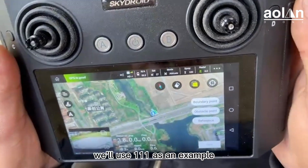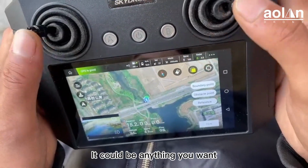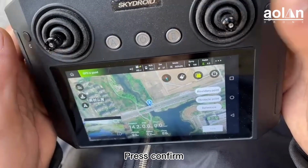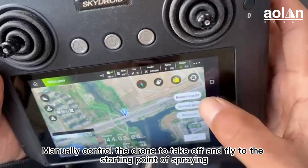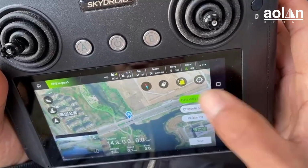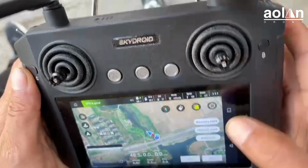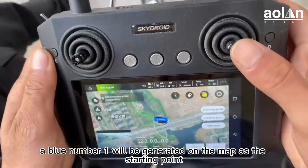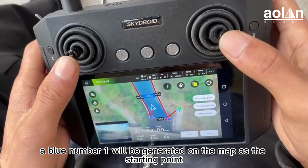In the video, we'll use 111 as an example. It could be anything you want. Press Confirm. Manually control the drone to take off and fly to the starting point of spraying. After hovering the drone, click Add Boundary Point. At this time, a blue number 1 will be generated on the map at the starting point.